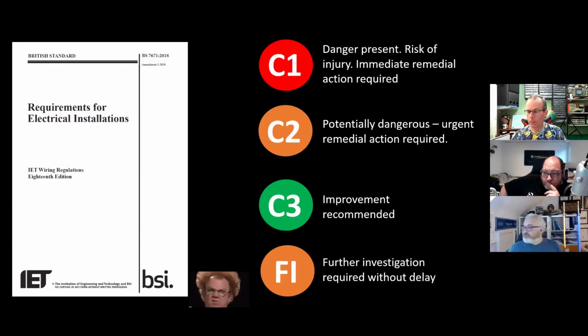And why not? The DNO intake is most certainly something that we need to inspect because it's in the schedule of items inspected. It's imperative for the applied safety measure, is it not? We do a Ze test, we do a PFC test. We make sure there's sufficient energy generated from the external earthing to trip circuit breakers. And obviously we look at the intake, the origin, the earthing, so that we can effectively have earthing and protective bonding and all that good stuff.